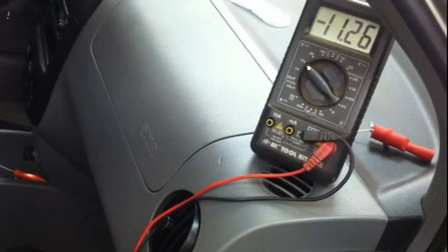Okay, what do we got for good voltage here? 11.54 volts. We go down, the meter drops to 28, 29, 27. That means this motor is trying to run on less than 1/4 of a volt, and you're losing that voltage between bad contacts in this switch. That's the bad one, that's down. This is the good one, up.